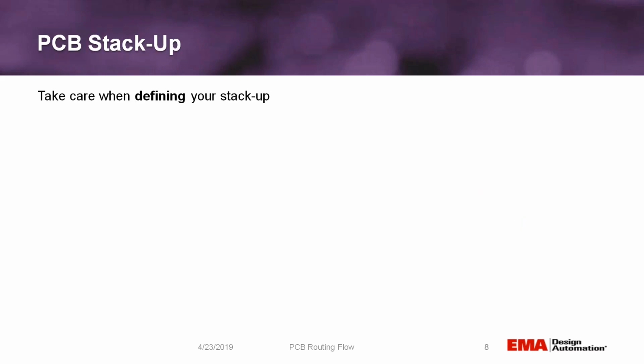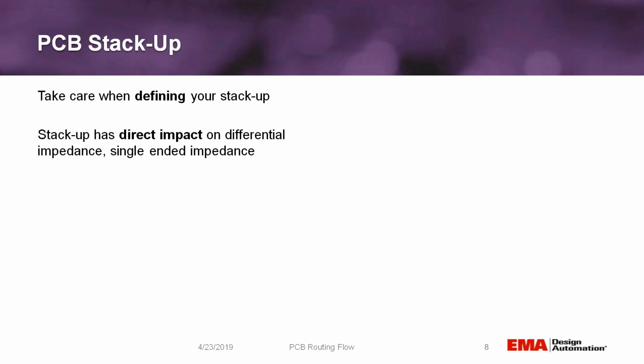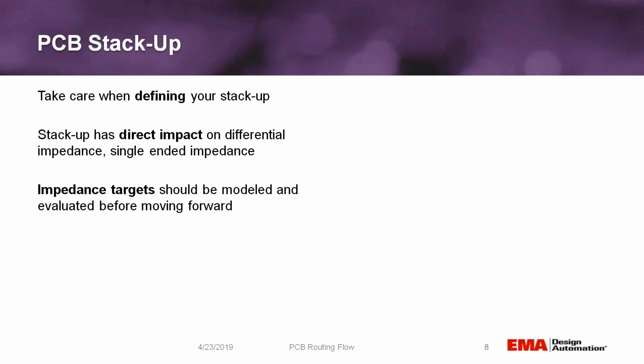You also want to take care in defining your stack-up. The stack-up can have a direct impact on your differential impedance and your single-ended impedance based on the dielectric constant of the material that you're using. You should also model your impedance targets before you go with that stack-up.